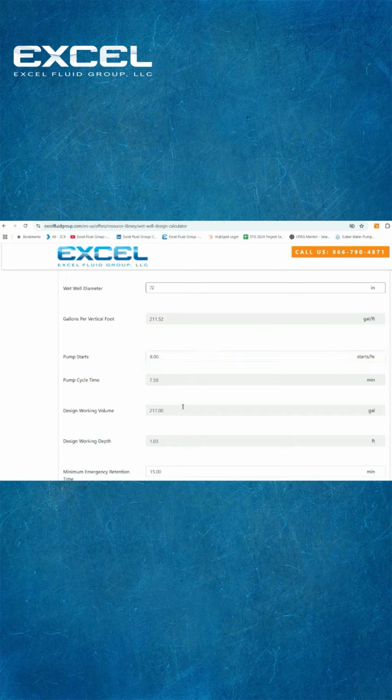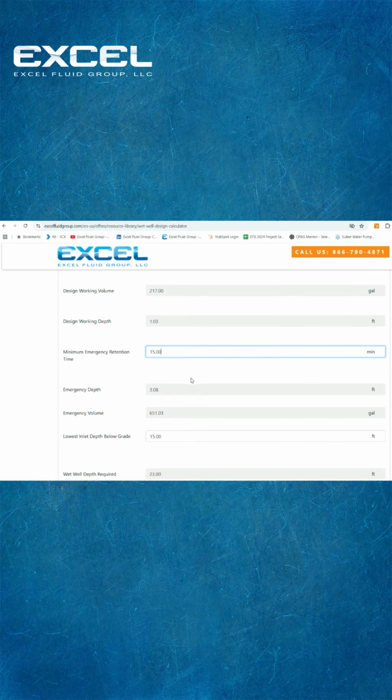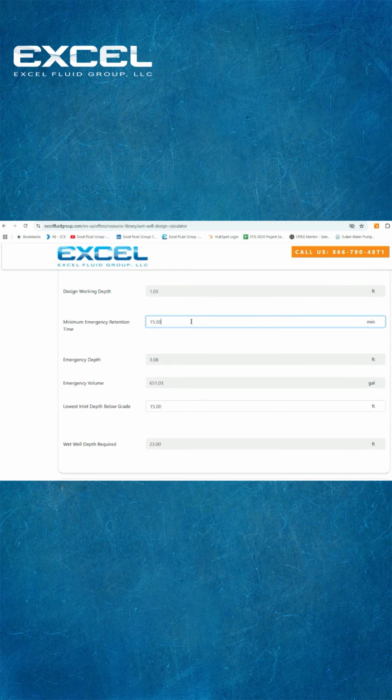Once the starts per hour has been inputted, then that calculates your pump cycle time and then the design working volume in your wet well and the design working depth. The next field that's user input is your minimum emergency retention time. This can either be as low as 0 if you have additional emergency backup equipment like a standby pump or generator. However, if we put in 15 minutes in this example, then that shows an emergency depth of 3 feet above your high water float elevation, and then shows you your emergency volume in the wet well.